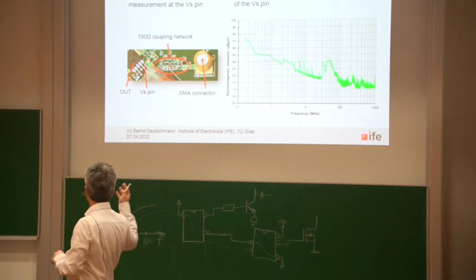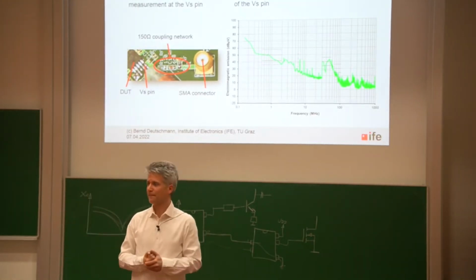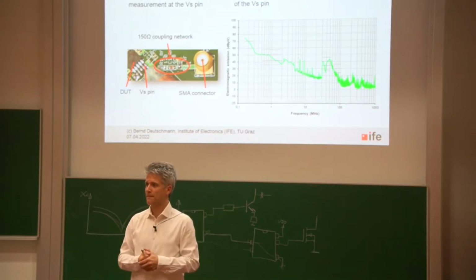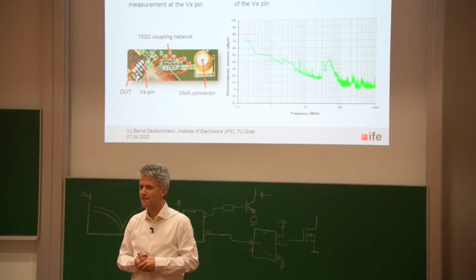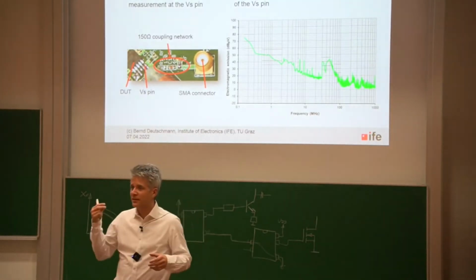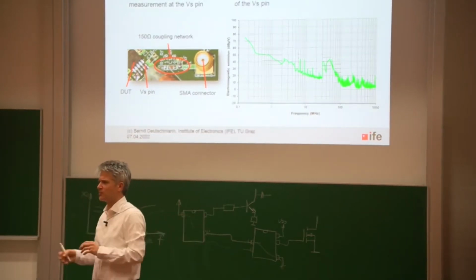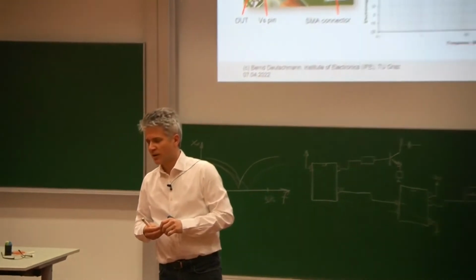So what's the main purpose of doing all these electromagnetic emission tests? Why are we doing this? Yeah, to see in which frequency range we have the most emissions, and maybe to track down then the source of this emissions. Yes, very good.